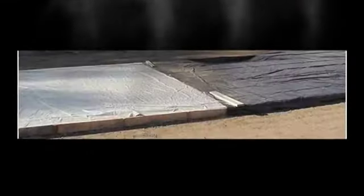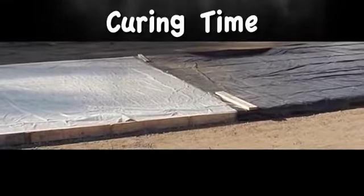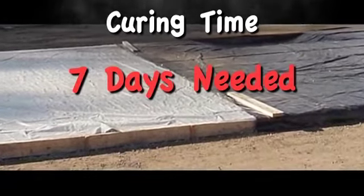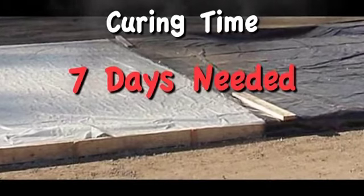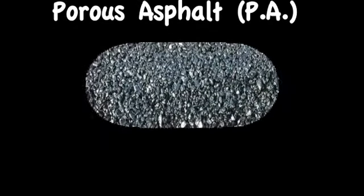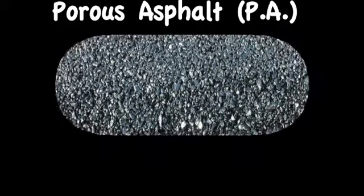Another difference between pervious and conventional concrete is curing time. Pervious pavement needs about 7 days to cure. This requires covering the entire surface with plastic, otherwise the surface will dry out too quickly and the paste will deteriorate. The fifth type of permeable paver is permeable asphalt, or PA.